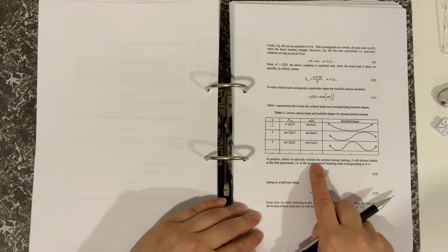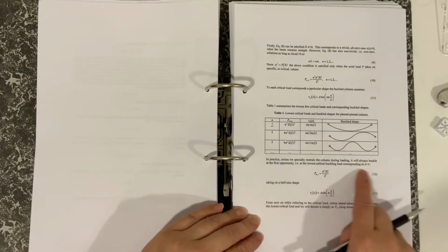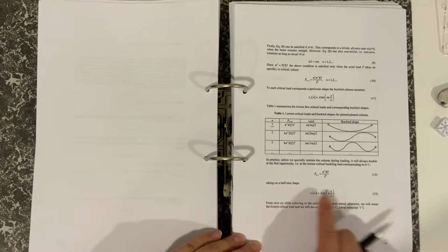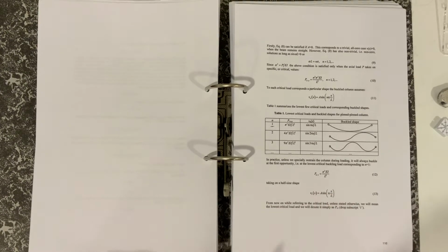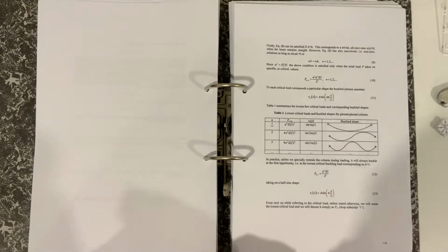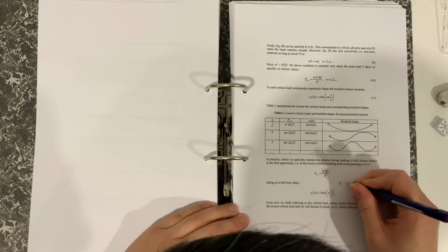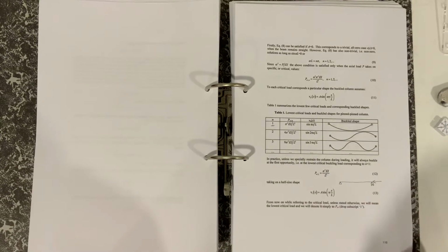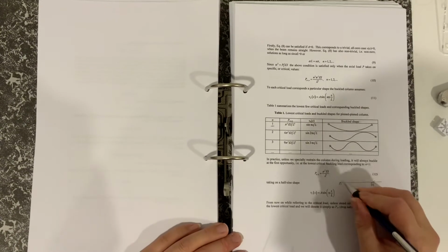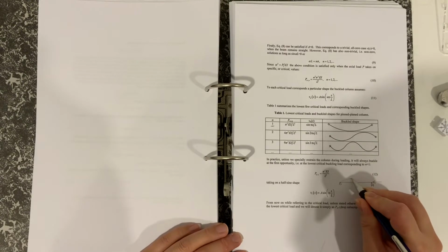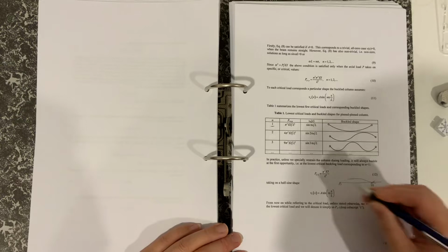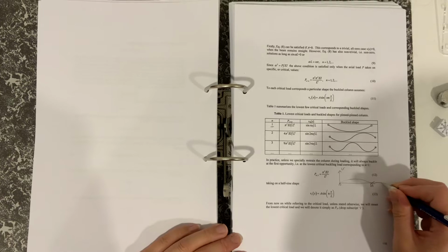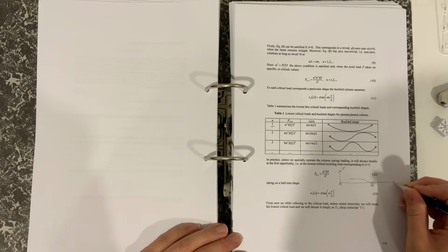And in practice, unless we restrain the column during the loading, it's going to buckle with n is 1, as I've just demonstrated, taking on the value of the half sine shape, A sin(pi x over L). So in other words, when I apply my axial force in compression to a column, it's going to buckle like that. And if I said that that's my axis v and that's my axis x,